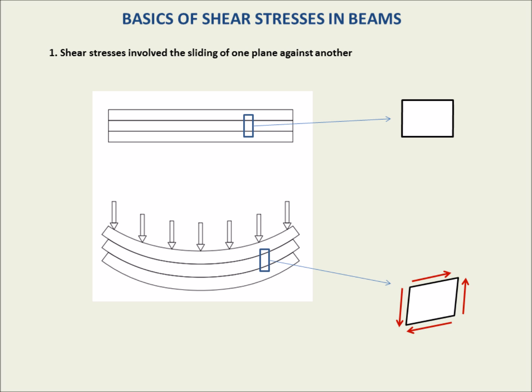the shear stress to the right and up, can be resolved into a single vector going to the right and the top. And similarly for the force going down and to the left. So now what does this look like? This is essentially what's going on. And what we're doing is we seem to be pulling apart this piece. We're pulling the piece apart such that if we continued, we would fail in tension along this line here, this jagged line I've drawn in a kind of 45-degree orientation.